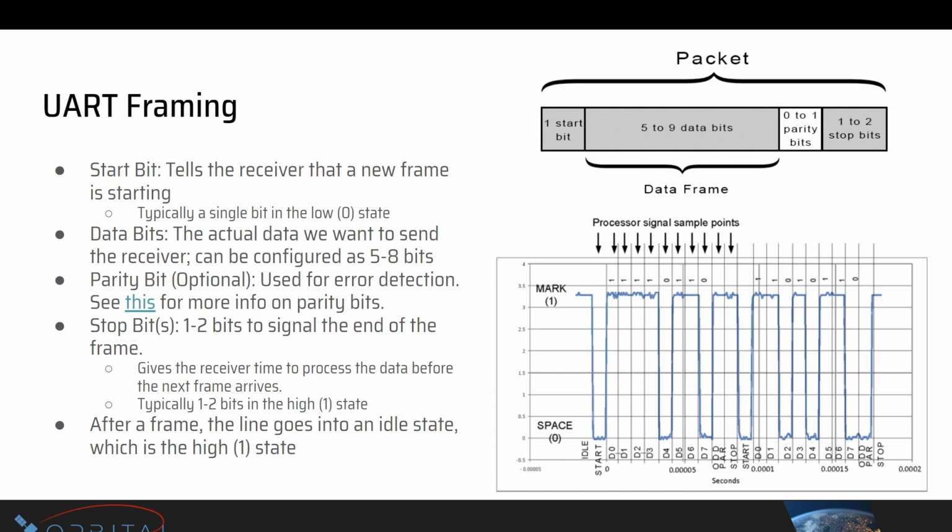If you have interrupts enabled in your MCU, it will. But you can imagine you have your actual MCU which you're writing code for, and it talks to a little internal module in it, which is a UART controller. In that UART controller, when the data bus goes low, there will be an interrupt that tells it to start sampling, and then it will read that data and send it to your MCU.